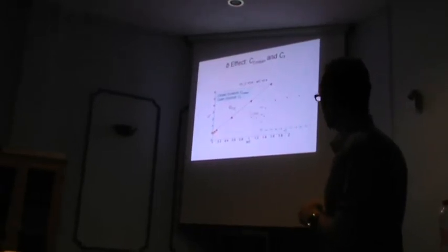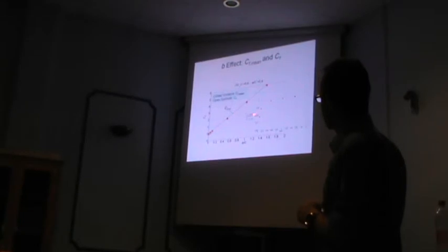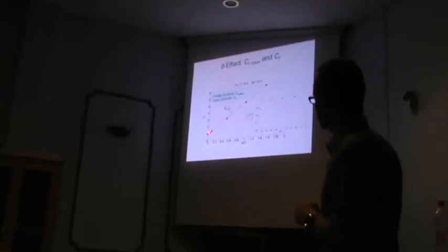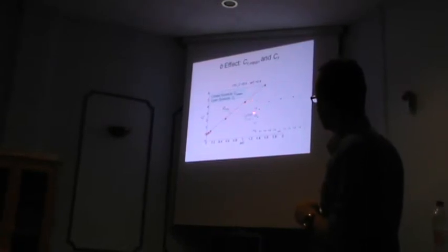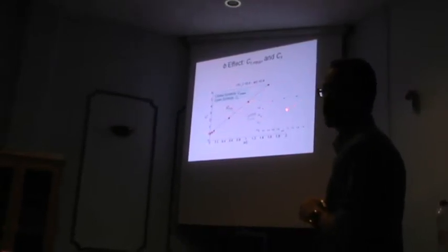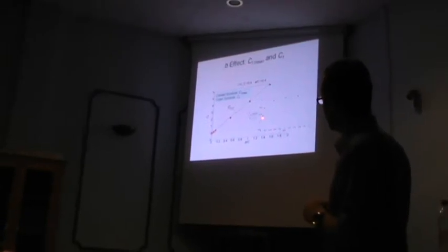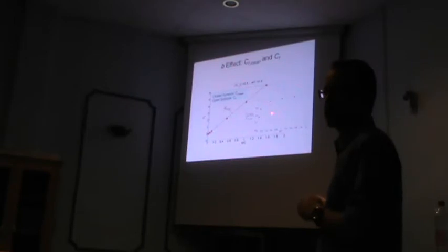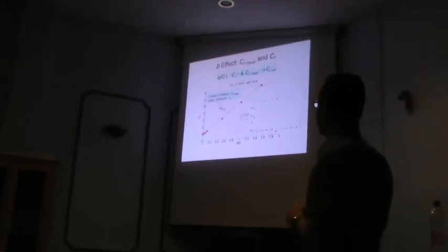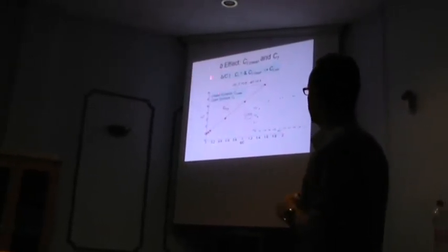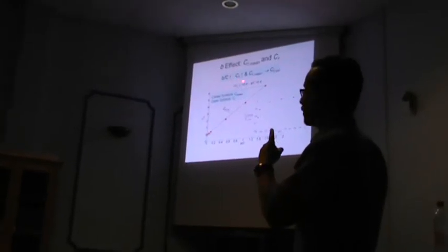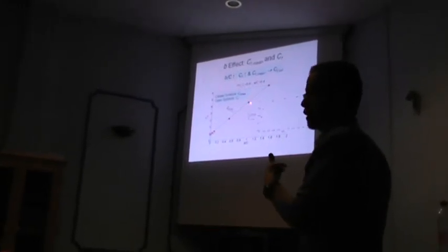If you look more closely, if you actually divide the CF mean by the vortex sheet limit, which is the dashed line, you can see it only really approaches that asymptotically. So the first 2 points do deviate a lot more than the ones at larger B over C. But the main lesson here that we learned is that as B over C goes up, that's actually good for increasing the thrust.